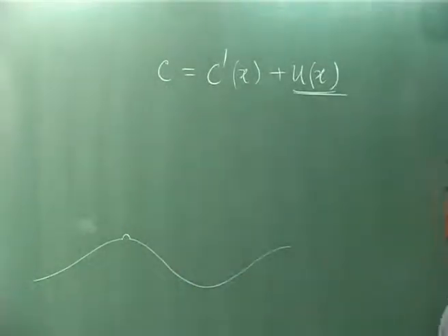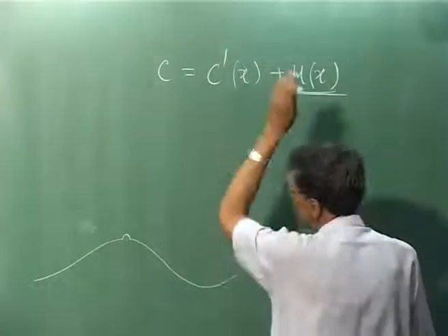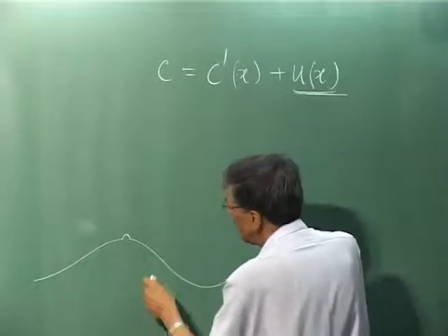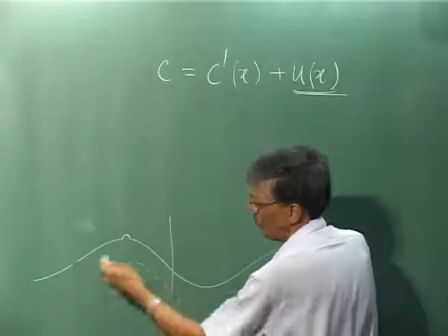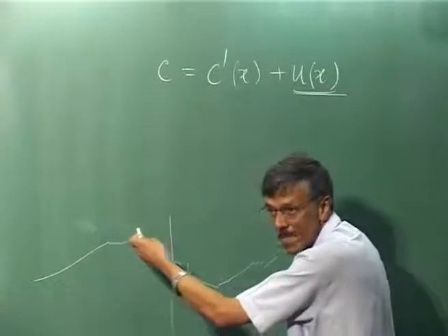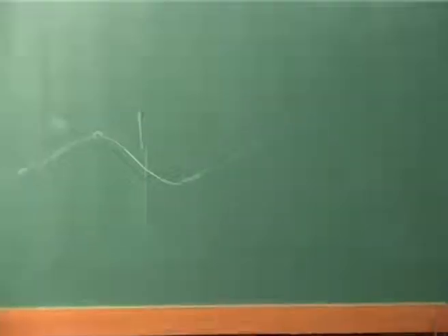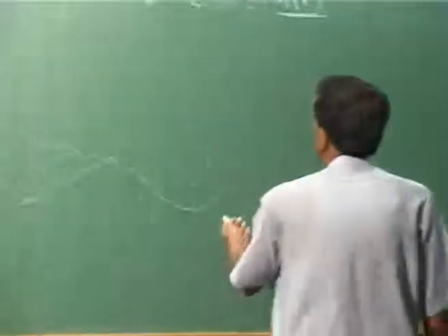What you are going to see is that with time, the presence of the nonlinearity is going to make this part of the wave, which has a positive displacement, have a velocity that, as we have seen, c prime is directly proportional to the square root of h. So, you will have a higher velocity compared to this part.